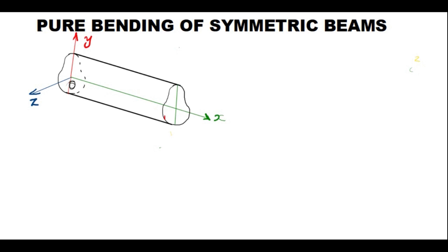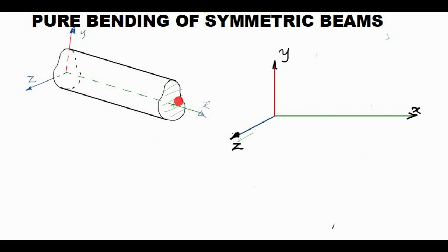Now we will come to the loading. We draw these xyz axes here separately for clarity. We have to consider the loading. In the case of beams, the loading will be perpendicular to this longitudinal axis, so the forces applied on the beam can be in this direction or any direction.